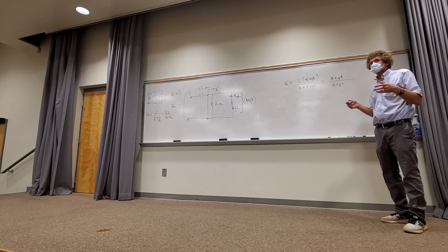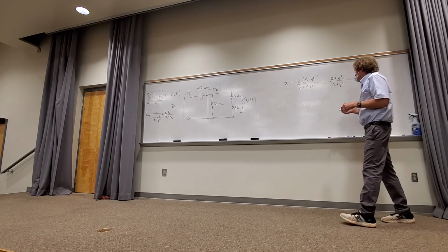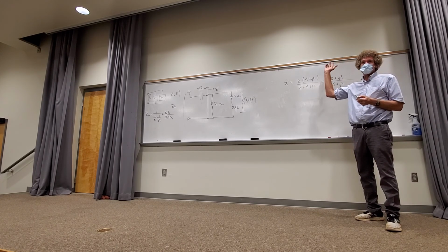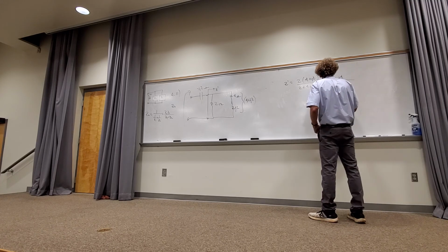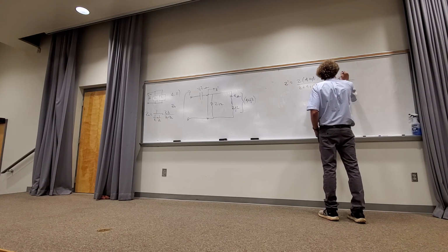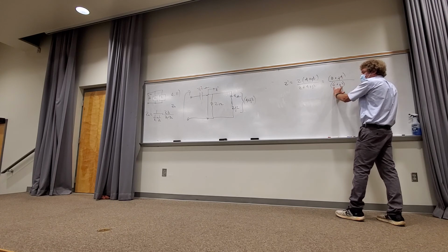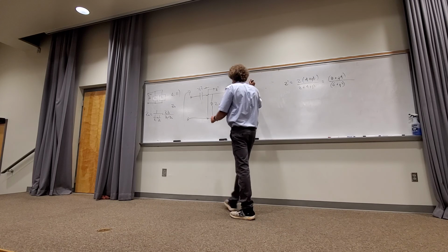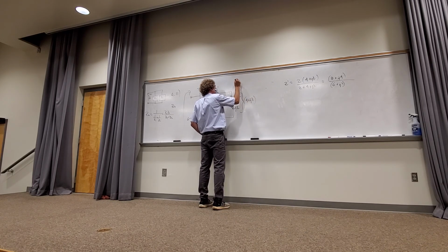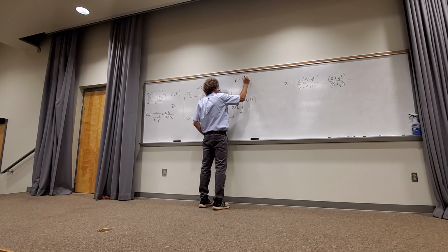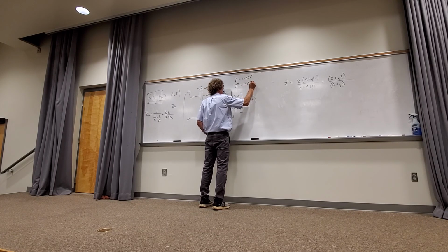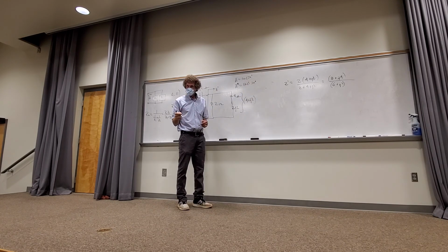The way it was done historically long ago, they would multiply top and bottom by a complex conjugate. How many have heard of the term complex conjugates? All right, so what they do is say, I'll multiply both of these by the conjugate of this. Conjugate just means, and this is something I better say, whenever you talk about a conjugate of something, if A is 10 at an angle of 30 degrees, A conjugated, that's the symbol used a lot of times, is minus 30 degrees. The angle changes.